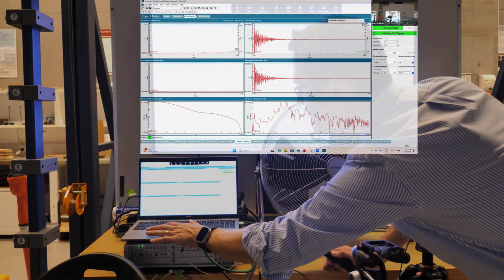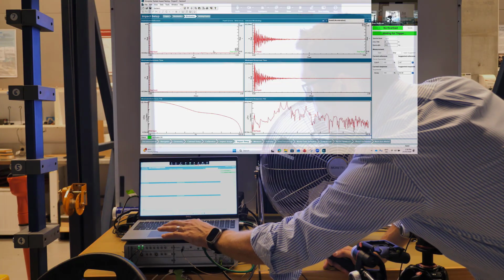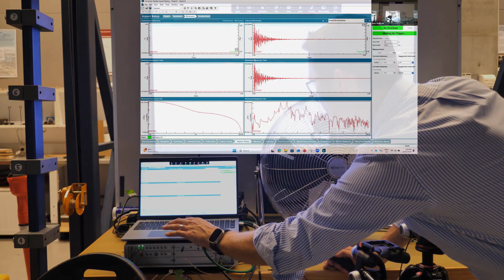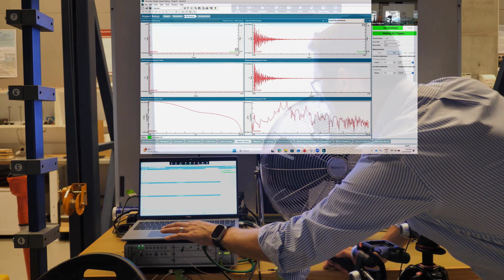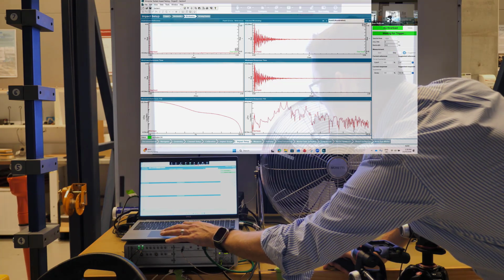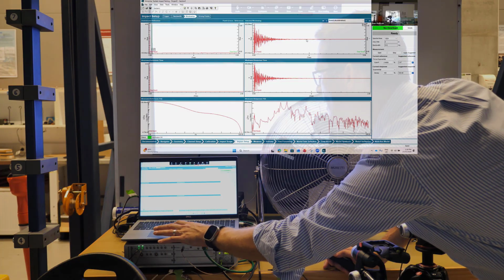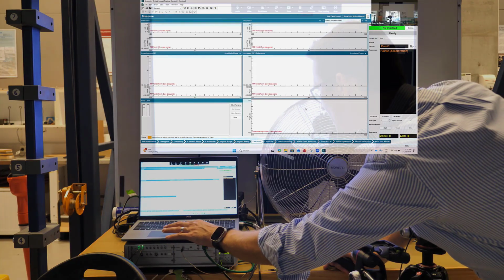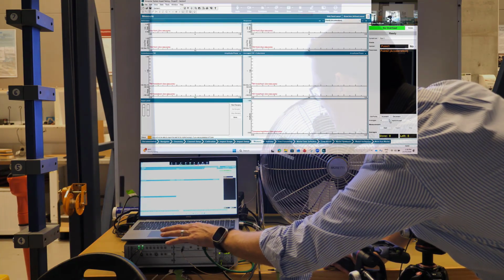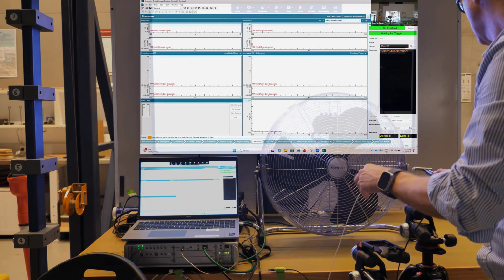The force window, the impulse force, is already finished well in advance of the end of that window. It does suggest a force exponential cutoff. So typically, if I've done a clean impact, I'll apply the selected settings. And then we can go to the measure sheet and do a measurement. So I'll just do 3 averages. Start that measurement. You can hear the audio feedback.